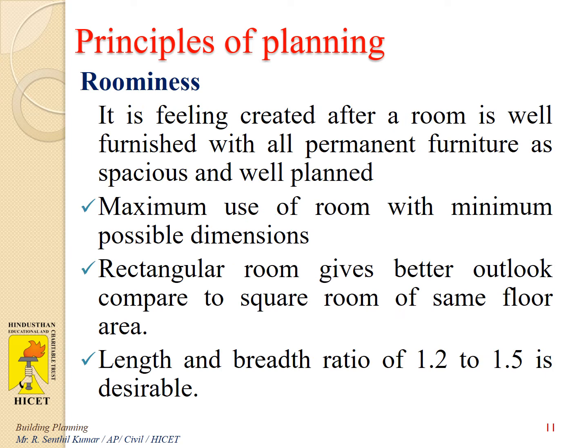And then roominess. It is a feeling created after a room is well furnished with all permanent furniture, as spacious and well planned. It means the maximum use of a room with minimum possible dimensions, and a rectangular room gives a better outlook compared to a square room of the same floor area. A length and breadth ratio of 1.2 to 1.5 is desirable, and when it exceeds 2, it creates a channel-like feeling. So a proper shape should be given for roominess.